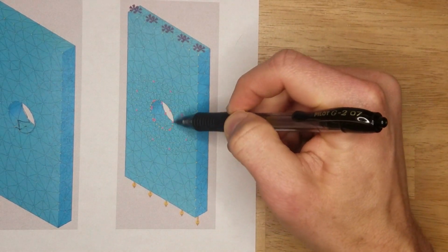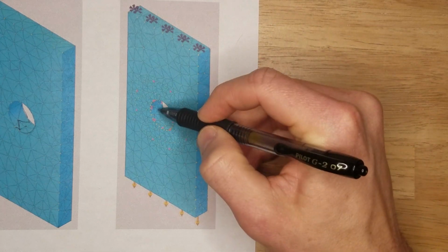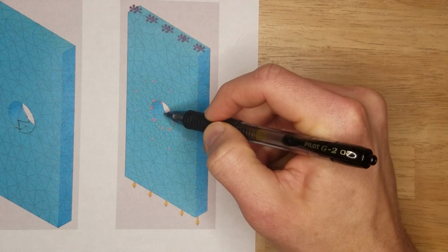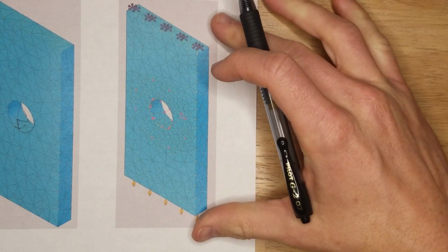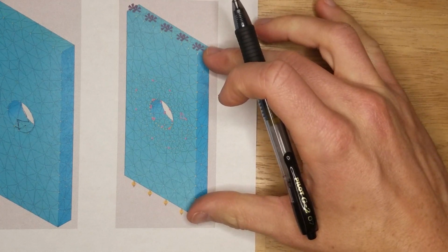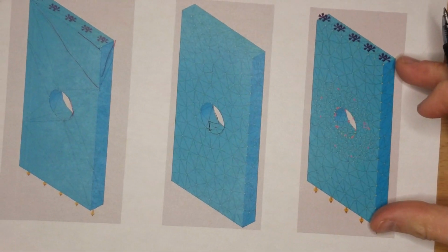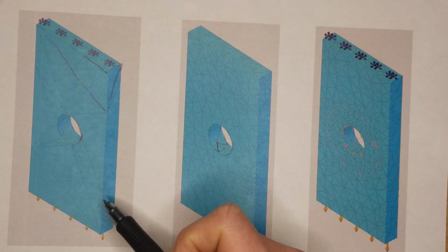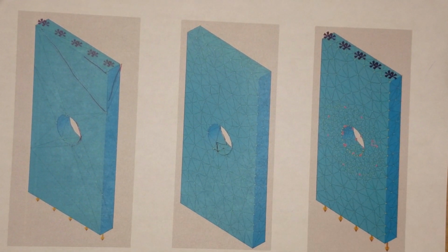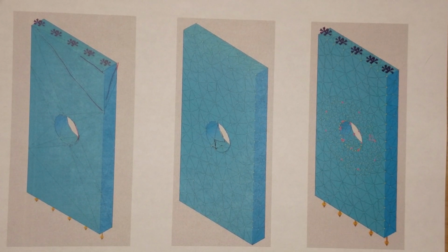I've got really good approximation here around the curve. I've got uniformly sized elements inside the curve. This is going to be really good accuracy in this run, but the computational time is going to be very slow in comparison to this guy. So we're all about balancing accuracy where we need it and computational time where we need it and not where we don't.